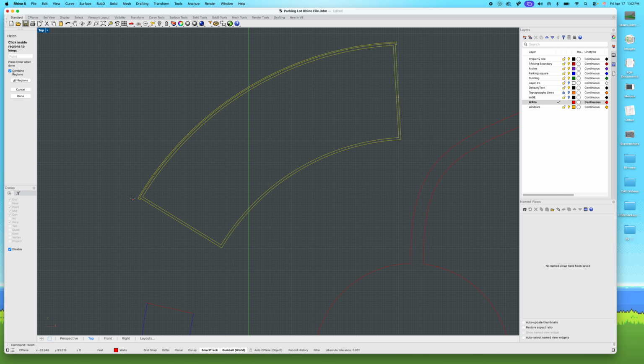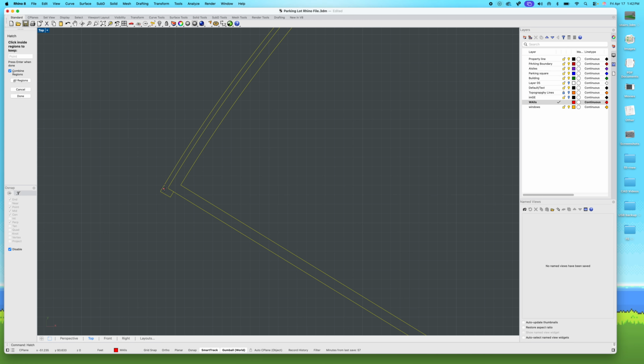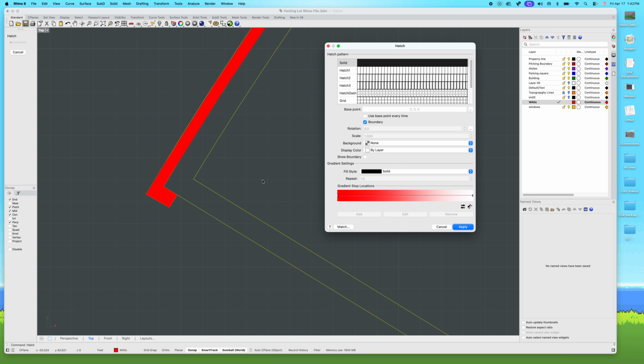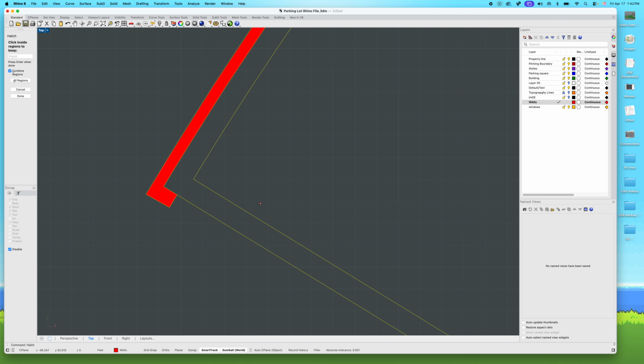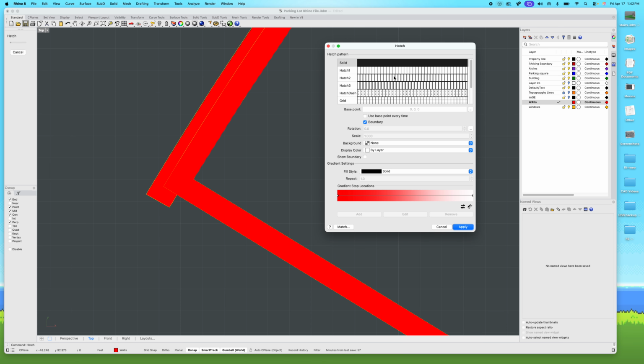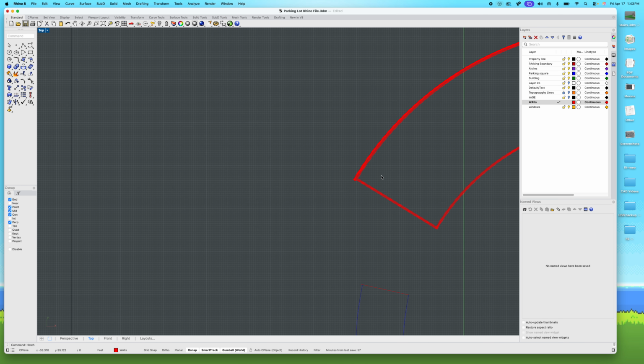And it's going to be like, hey, bro, what do you want to be filled in? Well, I may actually want both. So maybe I want this one to be stone, enter, apply. And I'm going to actually do it again and hit enter again. And maybe I want this one to be, I don't know, a series of lines. And maybe I want those lines to be at 45 degrees.